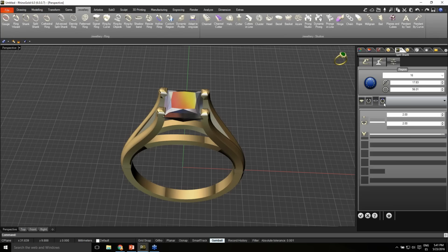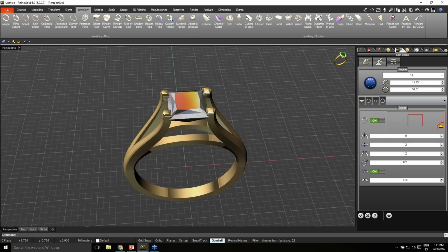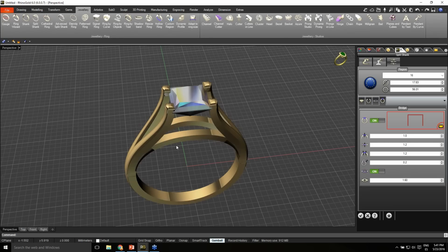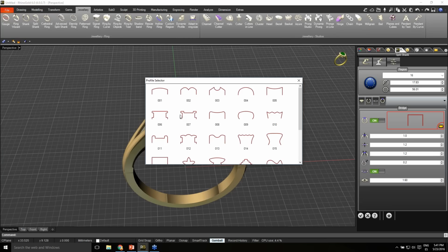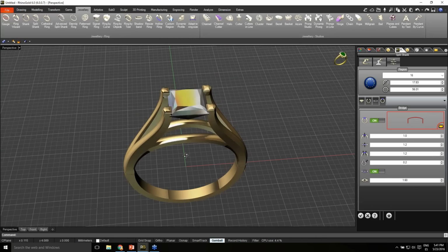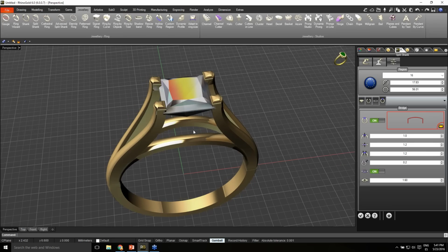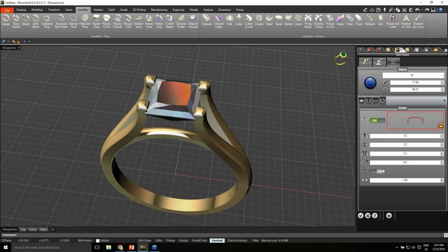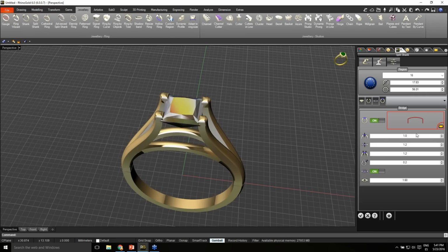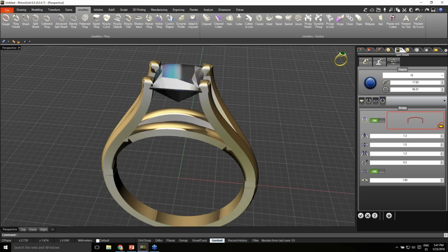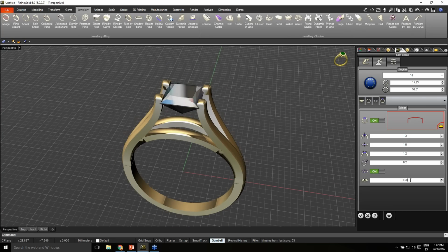And finally, the very last tab in this tool will be the bridge between the shoulders. So in this case, we have a square profile selected. Of course, we can use any from the library. We can also define if we want in the bridge a split bridge or just a single one. It will give us both possibilities. It allows us, of course, to define the thickness, all the measures, the width, the height for each one of these, and of course also the distance between them.